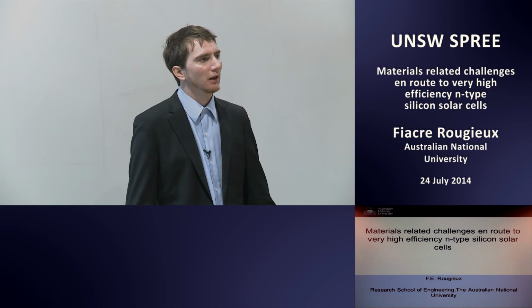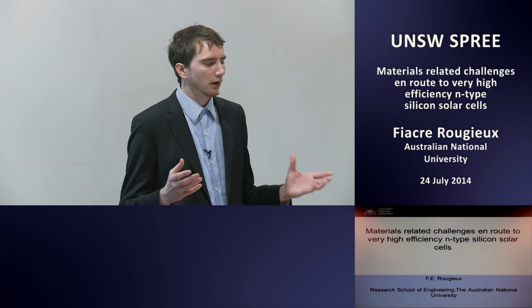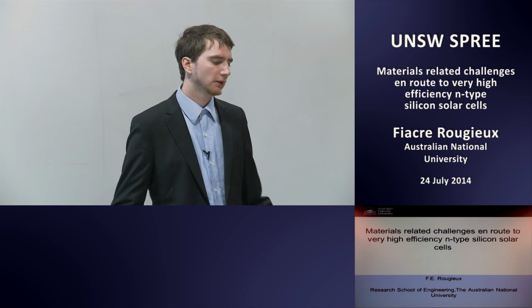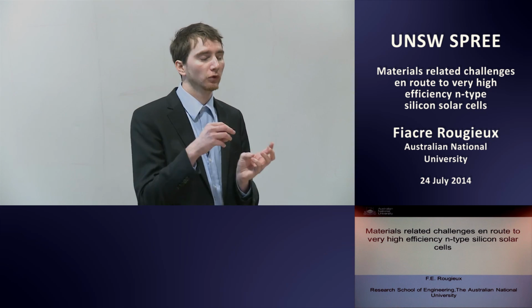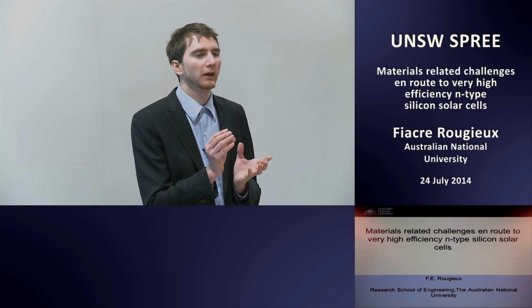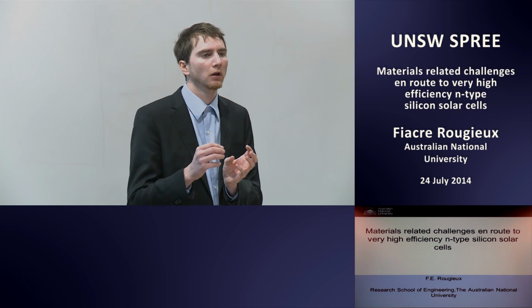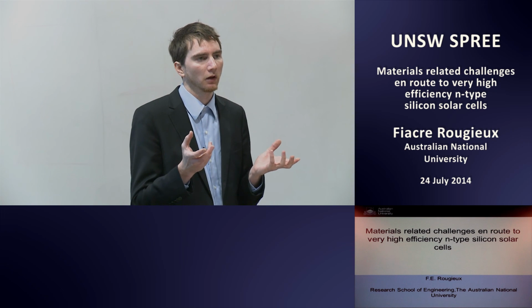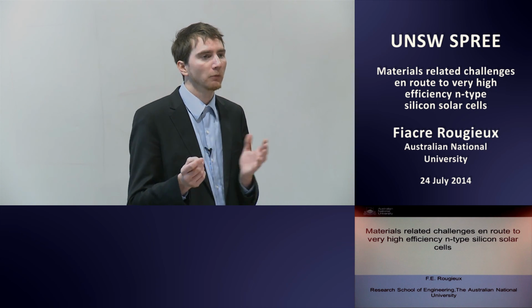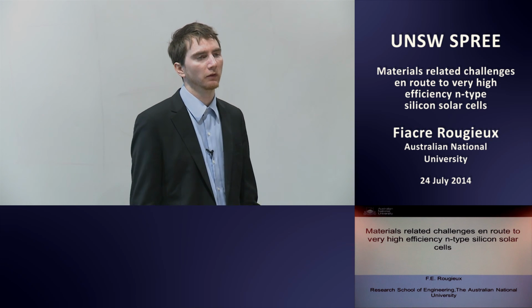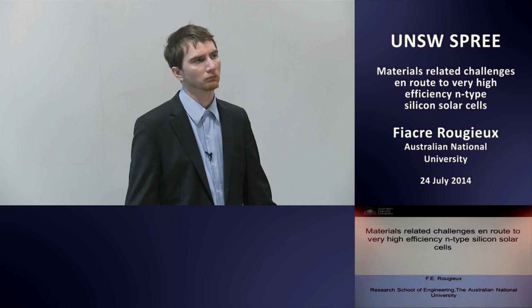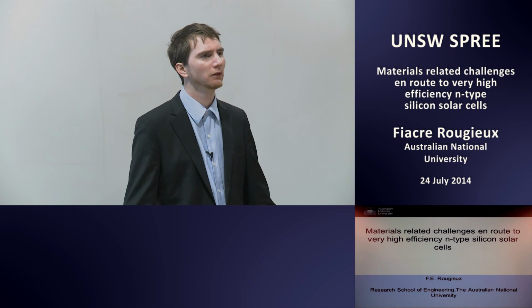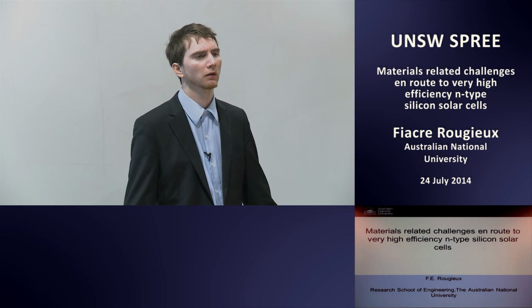Maybe if there was a film there, it would allow the incorporation of nitrogen more easily. But it's probably hard for the nitrogen to get into the wafer in the first place, and again, at 1,000 degrees, the diffusivity is not so high.